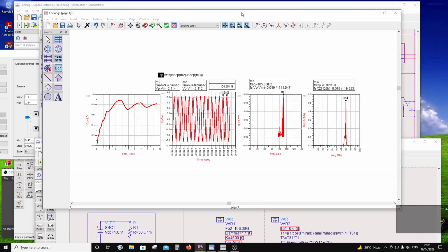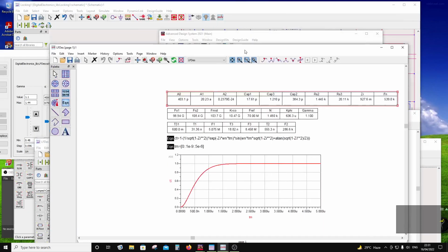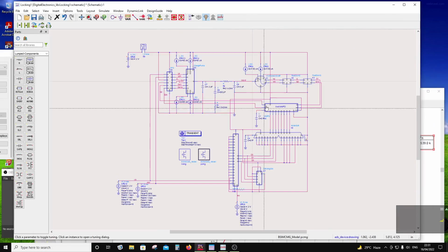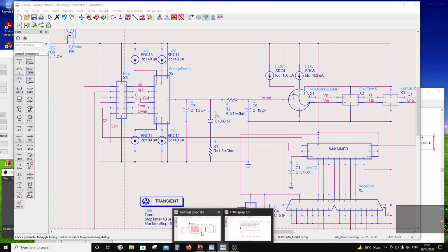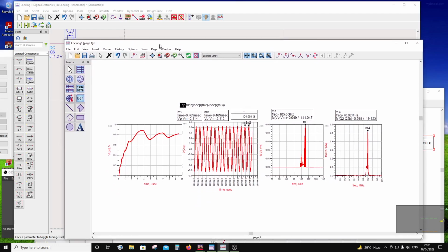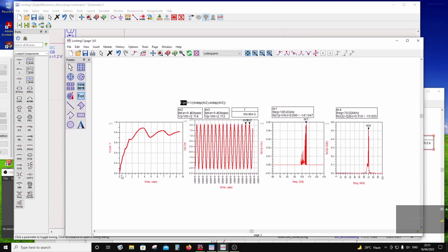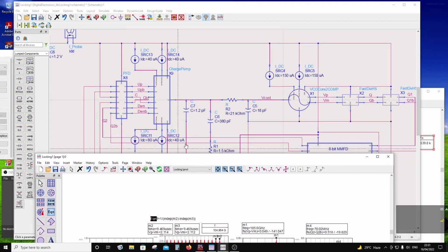They translate into the circuit over here. The loop filter is going to be off chip. This loop filter is for a certain damping ratio. For a given settling time and damping, you can see over here that there will be a settling time, a natural frequency, and a damping of this natural frequency.